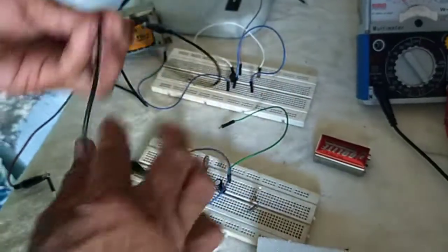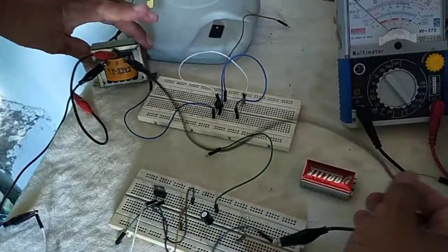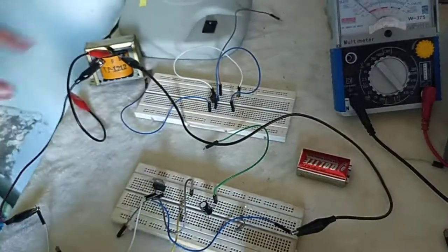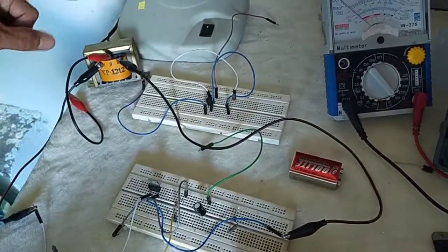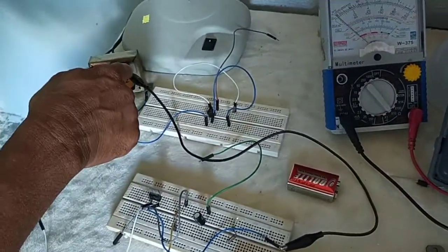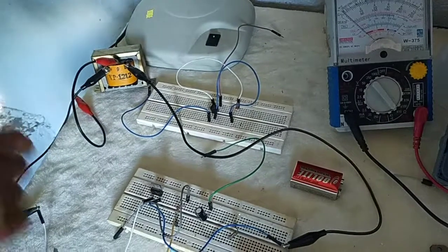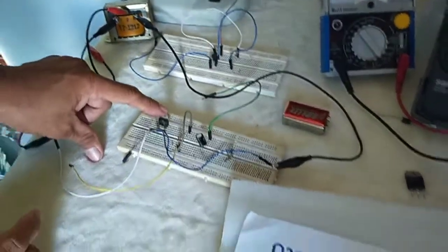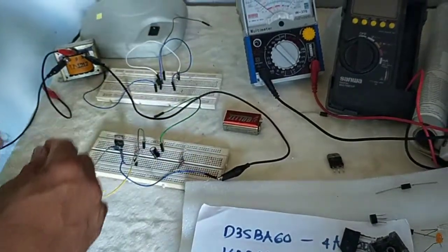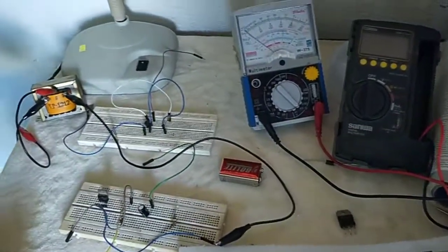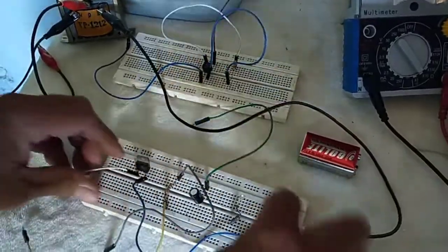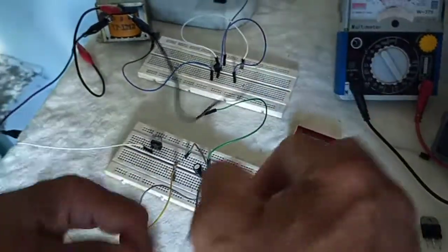Okay. Yeah, here, let us first perform a circuit. Dual. Okay. There are 3 terminals of this transformer because a full wave rectifier center tap type. The center tap type meaning the secondary winding of the transformer has 3 terminals. 12, 0, 12. So, when you are using dual rectifier, you have to use a transformer which is center tap type. Okay, let us connect here. Then the other one is connected here.